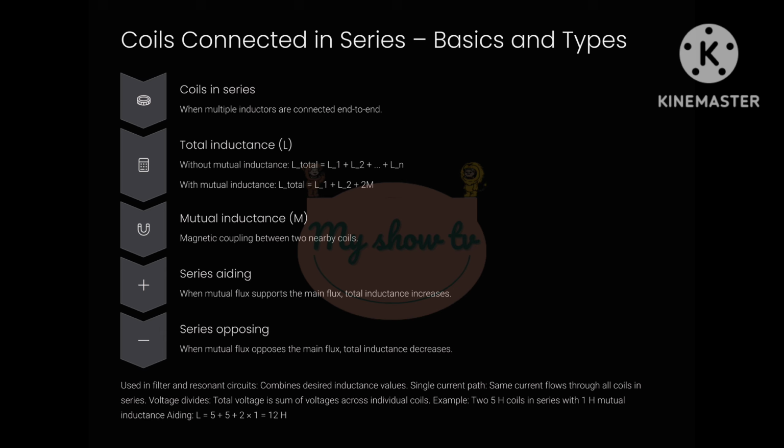3. Mutual inductance M means one coil's changing magnetic field induces voltage in another nearby coil. 4. In such setups, voltage divides across coils, while current remains the same. 5. Practical use, in filter circuits or inductive coupling where precise inductance is required. 6. Example, two 5H coils in series with 1H mutual inductance aiding each other. L_total equals 5 plus 5 plus 2 times 1 equals 12H. 7. Such combinations are common in power supplies and tuned circuits.